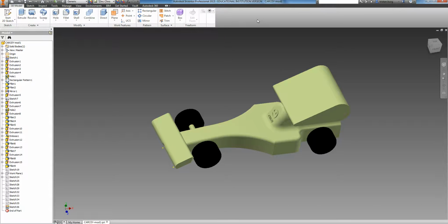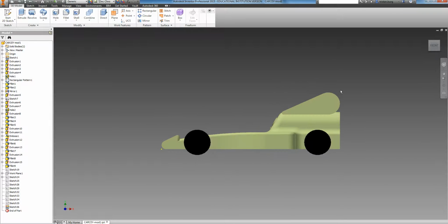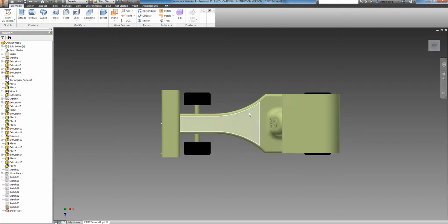And you might find in the flow diagram that is the absolute best possible arrangement of the back wing to make it aerodynamic. One thing you've got to be careful of though, look from the side, you've got to make sure this actually fits in the billet. The person in charge of Inventor is also in charge of making your car compliant and fit within the rules. Make sure the car doesn't extend longer than required, it can't be taller than the billet, and it can't be wider than the billet either. You've got those billet dimensions in your booklets. Just make sure when you've made your final car design it doesn't exceed the size of the billet.